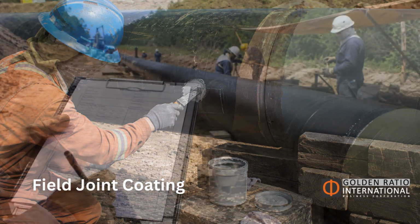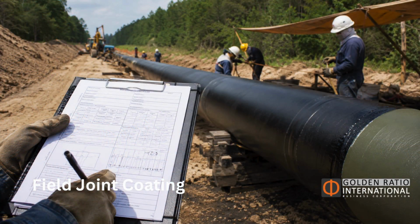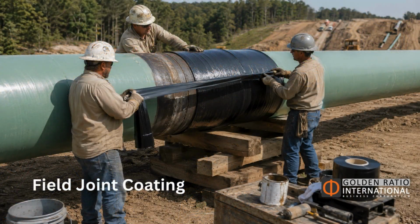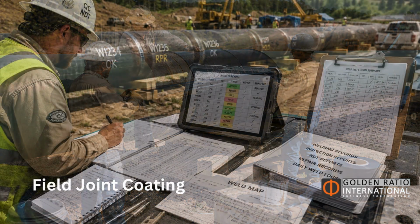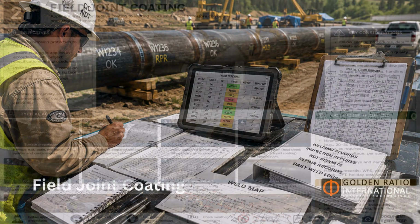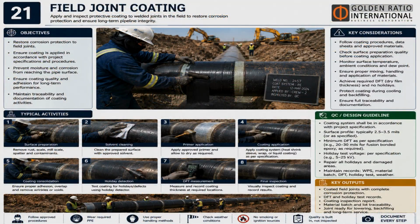Holiday detection, sometimes called jeeping, may be used to check for coating defects. This work is essential because the pipeline may operate underground for decades. A weak coating system can lead to corrosion risk, integrity problems, and future maintenance issues. So field joint coating may look small in the sequence, but it protects the long-term life of the asset.